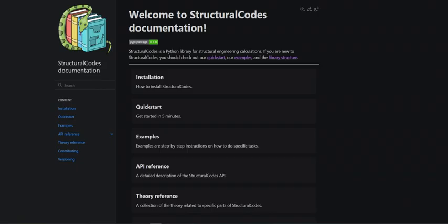Exactly. And so the functions that were used to create this plot, do users need to, like, how do they know what's available? I guess if you hover over your geometry variable, it shows what methods are available to them. Yeah, let's have a look at that. So we had the section. That's what wraps the geometry and exposes the methods of the section calculator. So if we do dot section calculator and then press a dot, now we see the methods that are available to us.